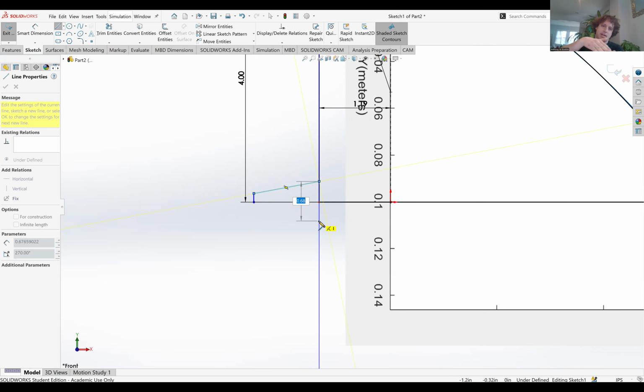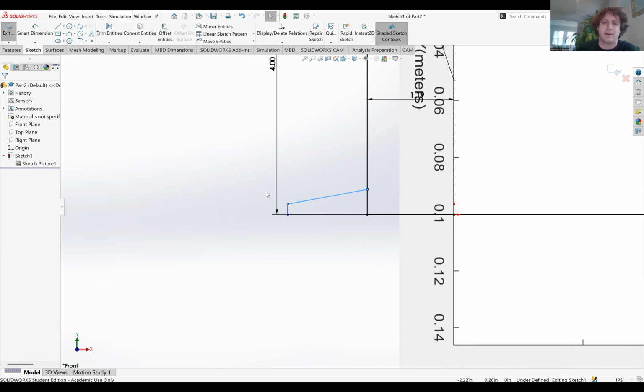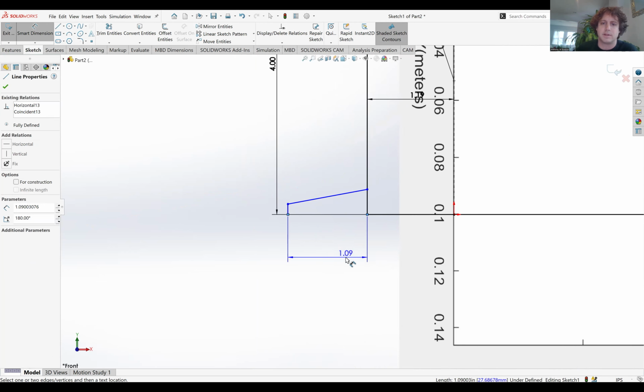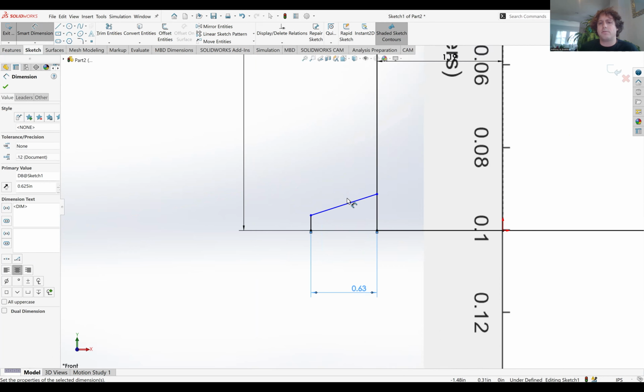If you make it go down to just a perfect wedge like that, it won't be that strong, and it'll kind of let water in. It should be said also that we will have a rubber gasket underneath to hopefully seal it a little bit better. But even still, you need to make this strong enough. So we're going to dimension that. We're going to make it 0.625.